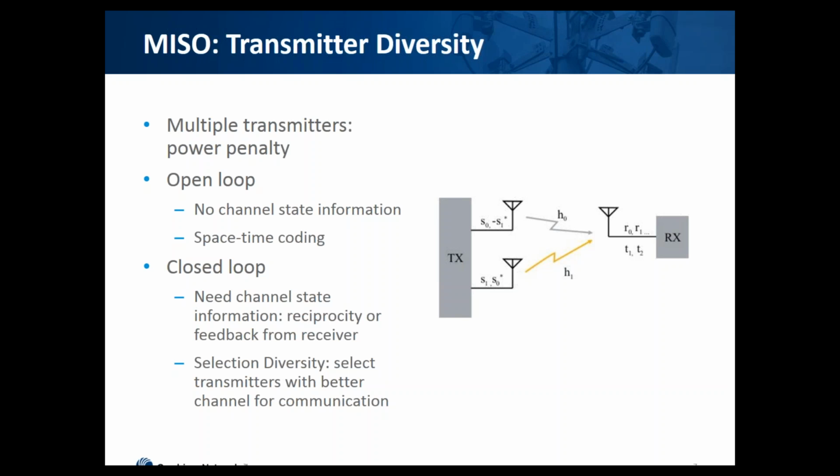The second method does not make any assumptions and just measures the channel. In this case, a known signal is sent from the transmitter to the receiver. The receiver then sends back the information of what was received. So the transmitter knows both what was sent and what was received. In this way, it knows what happened during transmission through the channel. If you do know what happens to the signal through the channel, you can use more efficient techniques. For example, if the transmitting device knows which channel is better, it can switch to using it and concentrating all the power in one path instead of splitting the power.